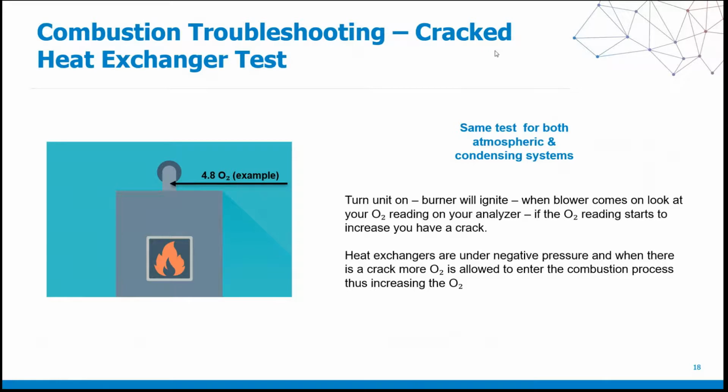But in a nutshell, your combustion analyzer, through the oxygen readings and through the excess air readings, can let you know whether or not, in a forced air system, you have a crack in that heat exchanger. It's a game changer because it levels the playing field. A very inexperienced tech can test for it, and an experienced tech can test for it. And it's a feature that an analyzer provides that can actually make you money as a service tech. So it's very important for everybody to understand that that is one of the important features.